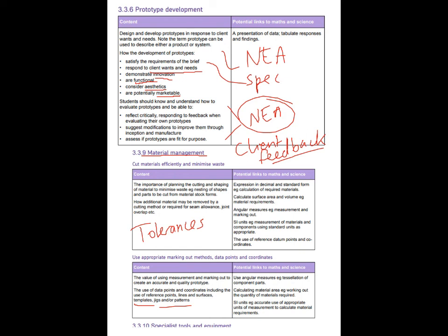When you get things laser cut out, for example, you might ask for loads of little circles to be cut out. You would put them as close together as you possibly can to reduce the amount of wastage. This process is actually called nesting, and it's kind of like tessellation, but it's just to think about how you can reduce the amount of material that is wasted in production.